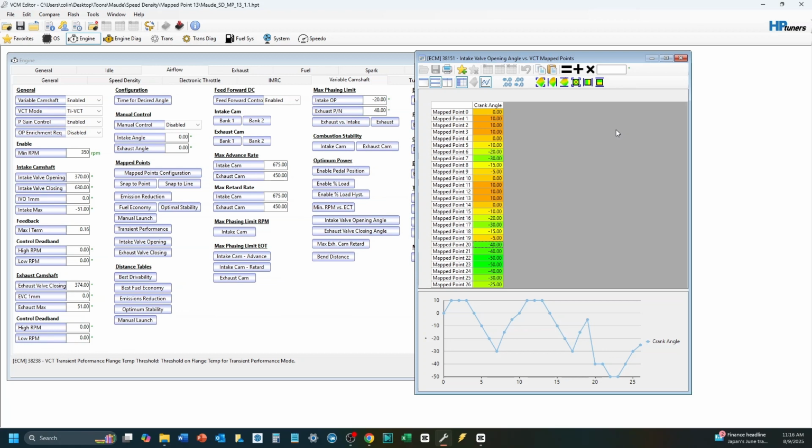The process I follow is I do my MAF first. And part of that is because I know that when I'm out doing the speed density, and I have my LTFT and STFT on, I have redundant overlapping MAF sensors, and it makes me feel very safe. Again, the pedal feels squishy. I can be doing WOT pulls. I know that everything's in order, and in my logs, I'm not seeing knock. I'm not seeing issues, right? The engine feels like it's perfectly safe.